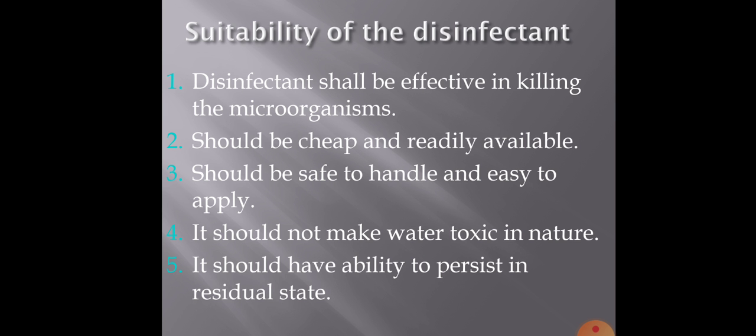So whatever disinfectant we are using for the disinfection process, it should still persist in some residual form in the water. The water that we are going to distribute to the public through the distribution system should contain the disinfectant in some residual form, so that whenever a recontamination occurs, it will again kill the bacteria that get into the water.